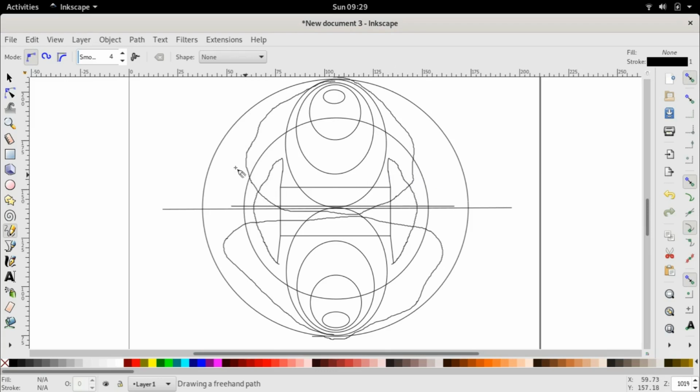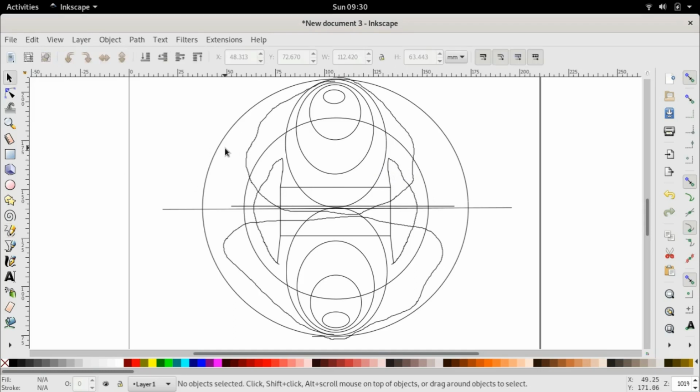Now, in this midsection, the air gap is the smallest possible. Here, the air gap is maximum. So therefore, in this case, the total reluctance faced by the flux is minimum in this midsection. Now, let me compare it to what happens if we rotate the rotor.